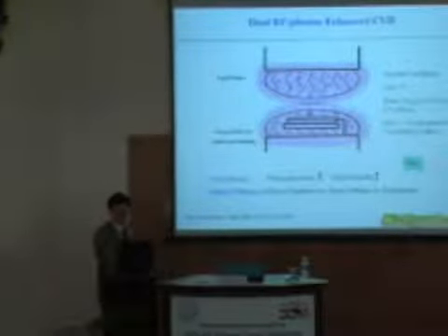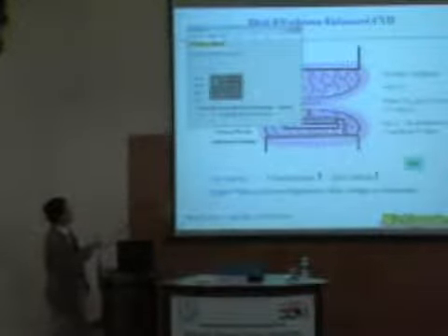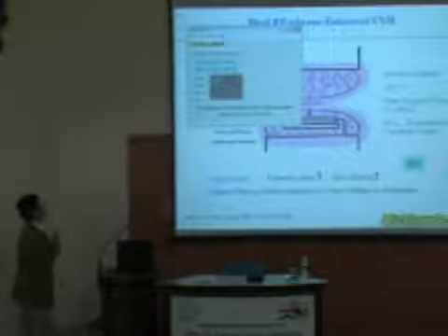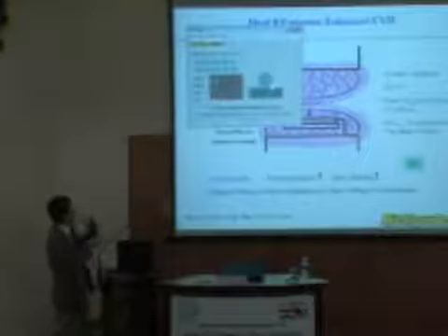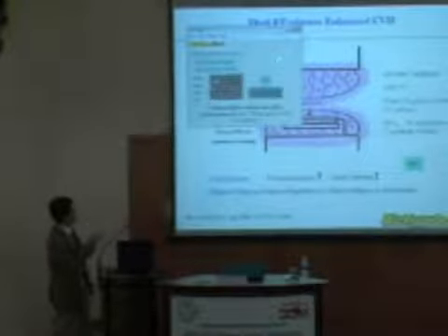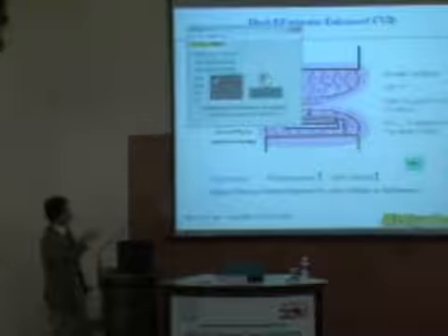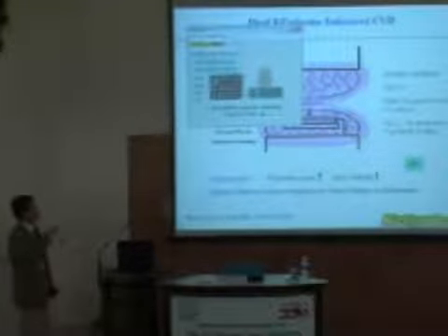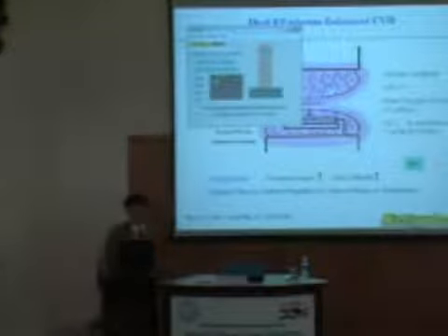Let me quickly show you how the whole process goes. Basically, you start with a catalyst on a substrate. This catalyst is nickel, and when you heat up the substrate, part of the catalyst will start to melt, and you use the plasma to generate growth species to shower down, and this carbon species will dissolve inside the catalyst. When this catalyst becomes saturated, the carbon nanotube will start to segregate out from the catalyst and form vertically aligned carbon nanotubes, as shown here. A very quick cartoon.